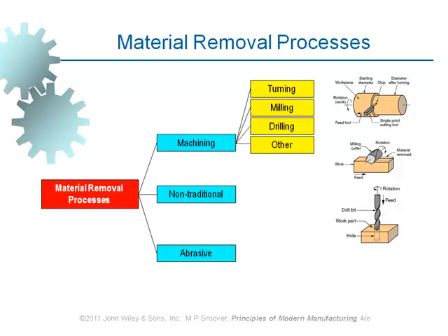However, in order to lower the cost as much as possible, it's a good idea to make use of a combination of manufacturing processes. For example, we can make use of casting process in order to bring the part to a shape and geometry which is close to the final shape and geometry, and leave just a little bit of material to be removed by a machining process.